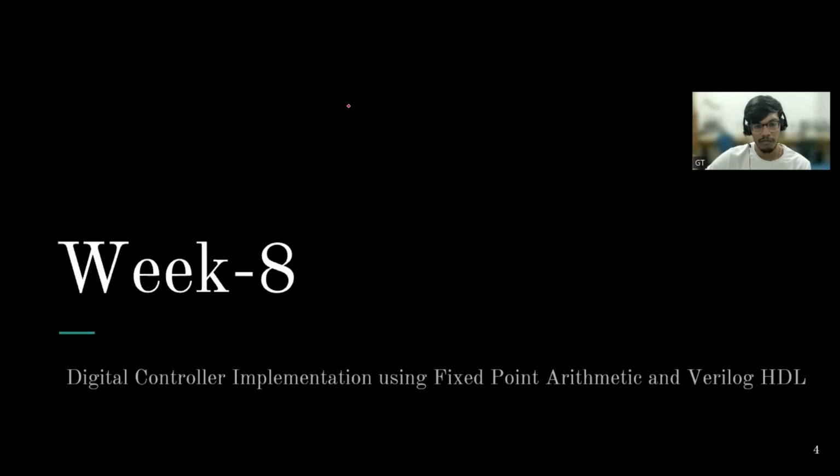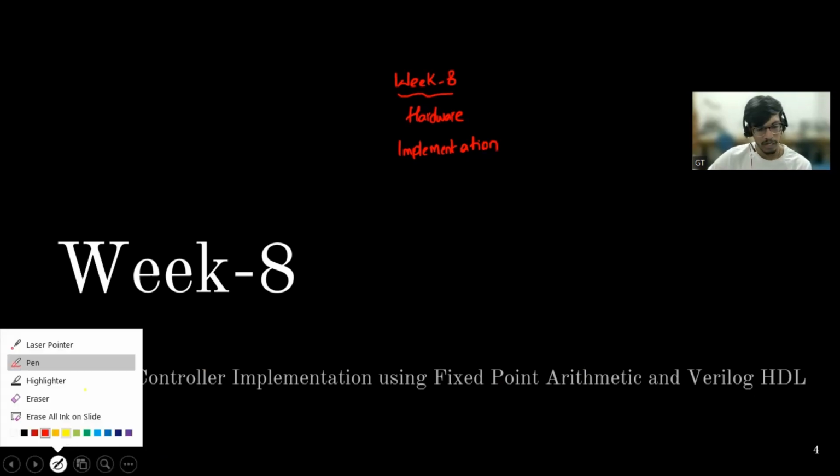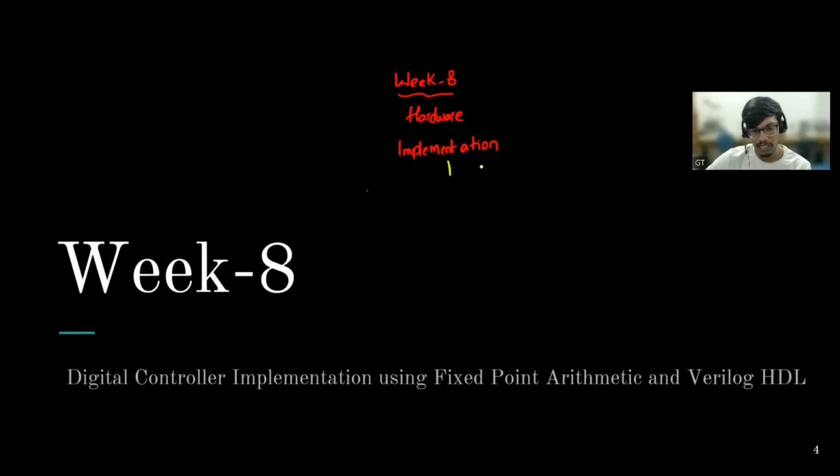From week 8, we will discuss the actual hardware implementation of different control techniques. Week 8 is about digital controller implementation using fixed point arithmetic and Verilog HDL. In week 8, Sir has discussed 3 modulation techniques: one is the digital voltage mode control, and the other ones are mixed signal current mode control, and digital PSM.